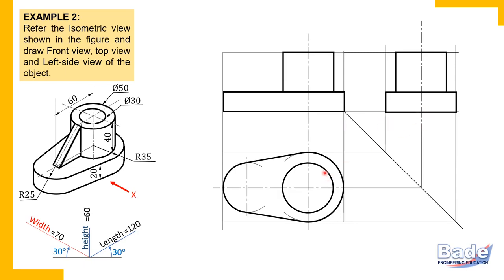Okay. Now this cylinder has a hole. It is a circular hole. Its opening circle appears in the top view, so draw that. Radius is 15. Diameter 30 means radius 15, so use radius 15 mm. Complete the circle. It is a coaxial hole, that is, the axis of the hole and the axis of the cylinder are the same. Therefore use the same center and complete the circle.